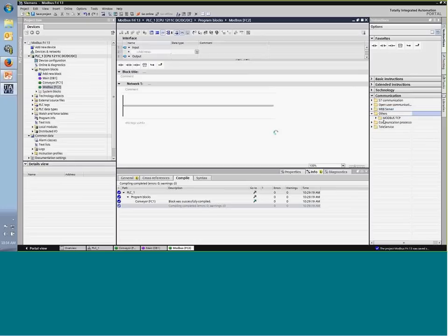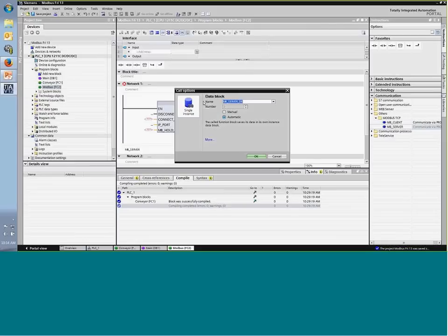And if we go under others, we have Modbus TCP. Under Modbus TCP, we see we have two predefined blocks, which are communication via Profinet as a Modbus TCP client or a Modbus TCP server. We had a CM1241 Modbus server before, so let's go ahead and drag a Modbus server block right there.